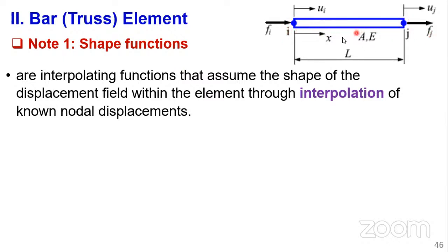Okay. So sometimes we are saying this interpolating function that we assume the shape of the displacement field based on the type of element that we are dealing with, of course. And I went ahead slightly when I talked of the beam member or the beam element. Because for the beam we anticipate to get the deflection, you look at the curvature of that deformation, and then we said it wouldn't be far-fetched to assume the displacement function as being maybe cubic or quadratic, something like that.